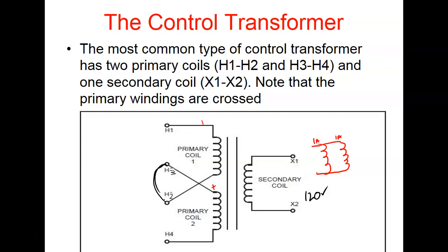We have 3-phase. We have a 3-phase Y connection over here. A Y connection got that name because the transformers are drawn like this. And it's 3-phase, and this is where we get our 3-phase from. One of them is going to be labeled L1, one L2, and one L3.